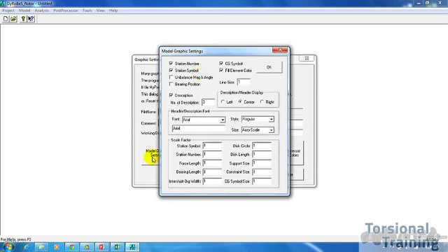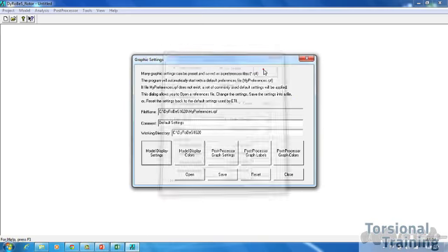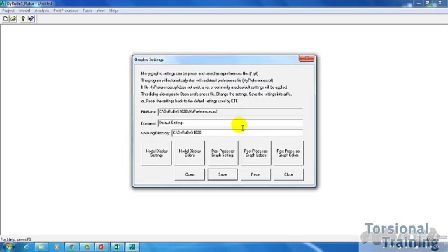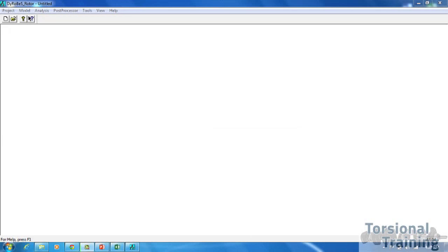Go ahead and click on Model Display Settings, and under the Model Display Settings there's a tab called Description. Make sure it's checked. In my case it is checked, and hit OK and hit Save, and it'll open up a Save As window, and you'll be able to save your particular preferences of how you'd like certain views within Dyrobes. As we get into more detail, you'll see how this is very useful. So go ahead and click Save, hit Yes, and Close. Alright, so let's get started.